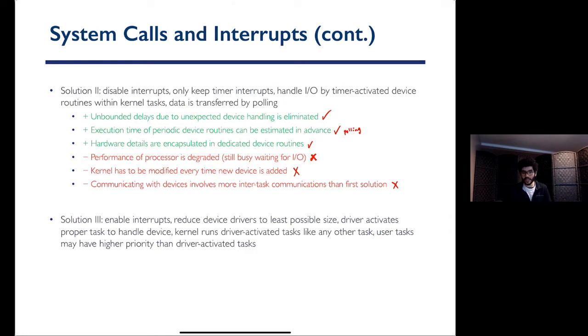So we're not going to handle the interrupt immediately. We're going to create a new task. Remember, this is very important. When I was talking about general purpose operating systems, I made it clear that interrupt handling is not a task. It's not a thread because it's not schedulable. Now I'm changing that. So we're going to run it immediately, but we're going to ask our interrupt handler to create new tasks to then go and handle the interrupt.